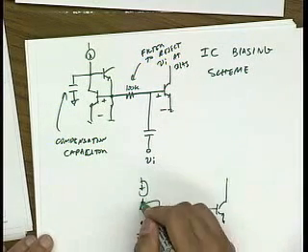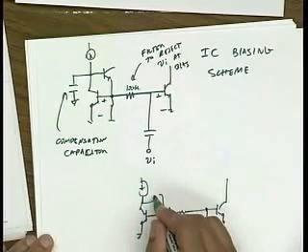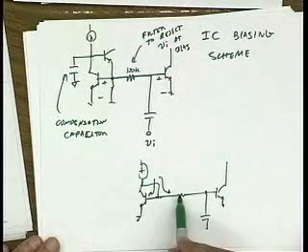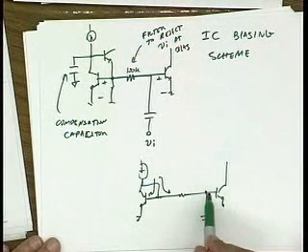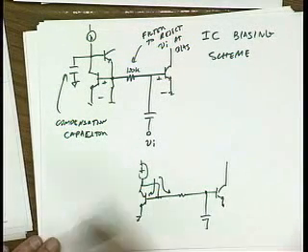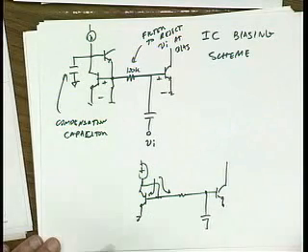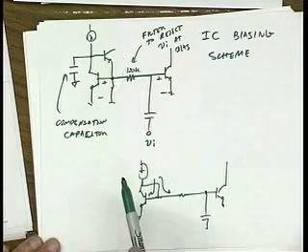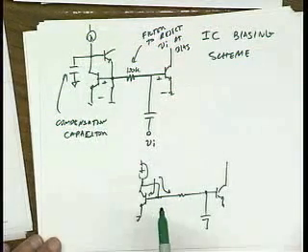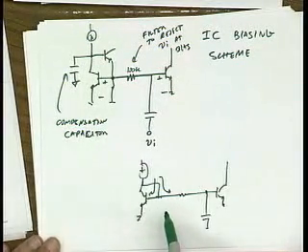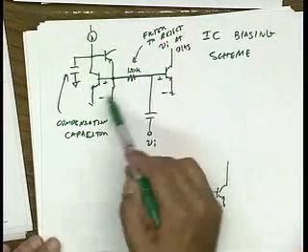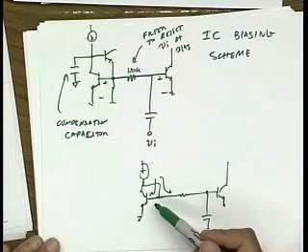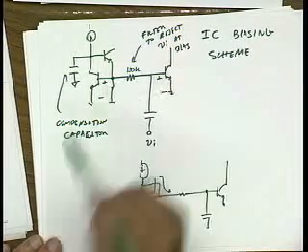The difference now is that, first of all, I have base current. And if base current flows through this resistor, it varies the VBE of this device, right? So that's kind of bad. I'd like to get rid of that because base current varies over temperature a lot due to beta variations. So here, this is basically a helper transistor to lower the base current. And in CMOS technology, that's not an issue. But the other nice thing about this shunt feedback is it lowers the input impedance. Here, the input impedance is about 1 over gm, right? Here, it's much lower.